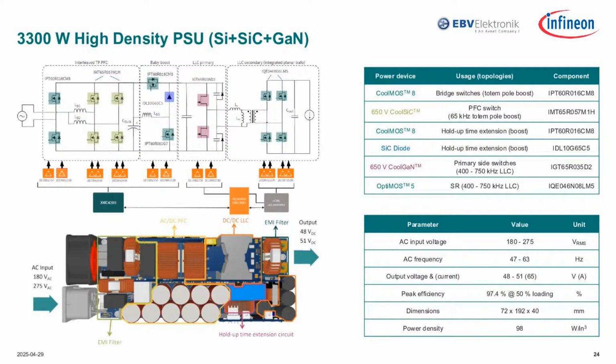That means you are looking for really high switching frequency, low driving loss, and in some cases you need to avoid hard commutation conditions. That's why the gallium nitride device is a perfect fit in this stage, particularly on the primary side, to fulfill our design requirement in the high frequency LLC half bridge.